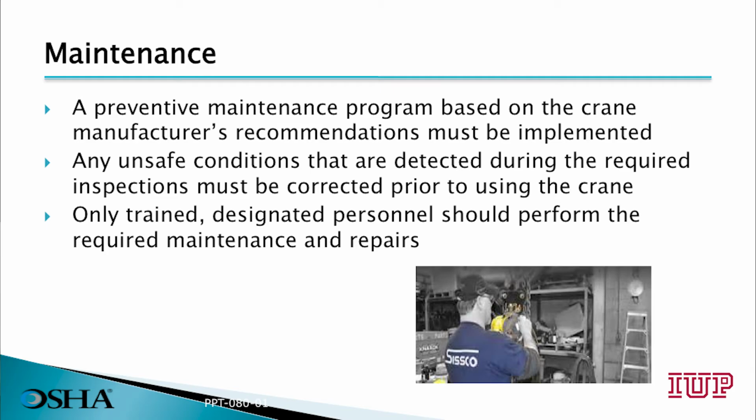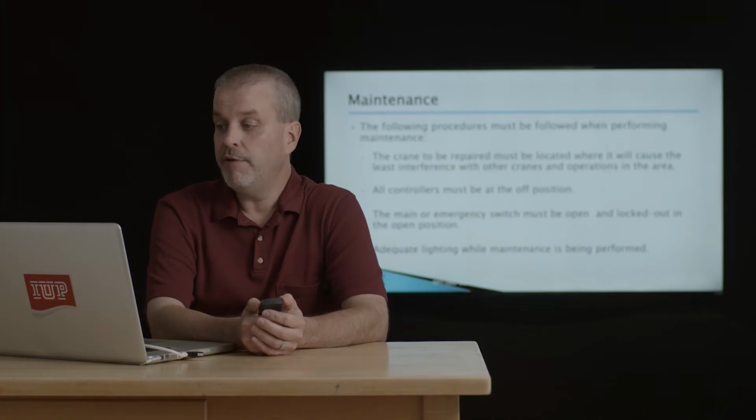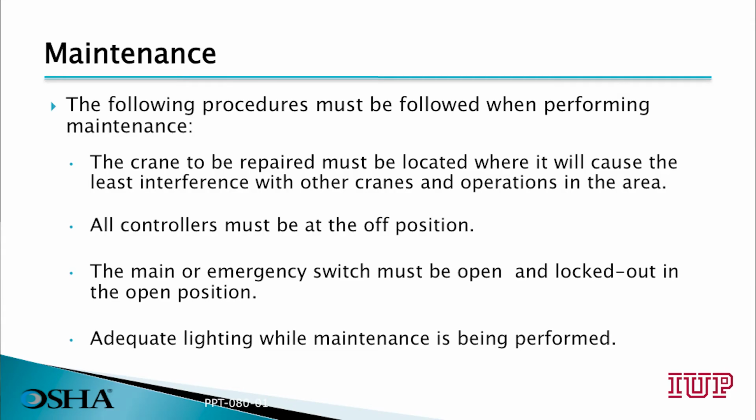Only trained designated personnel should perform the required maintenance and repairs. The following procedures must be followed when performing maintenance. The crane to be repaired must be located where it will cause the least interference with other cranes and operations in the area.